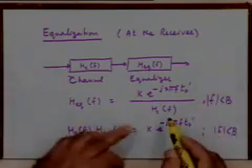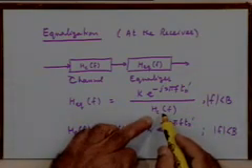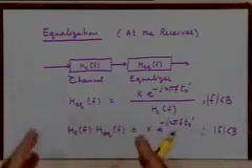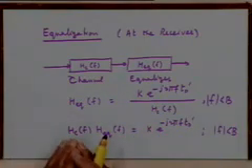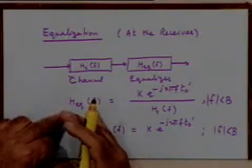Suppose the channel H_C(f) has a null in the range of some frequency components within the message bandwidth of interest. Over a few frequencies, or in the neighborhood of some frequencies, the channel exhibits very deep attenuation. Suppose it happens. It can happen, right? Then what will be the required equalizer characteristics at those frequencies? Very large amplification of those frequencies.